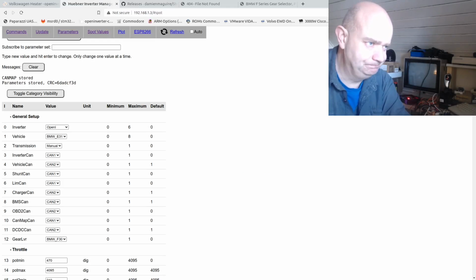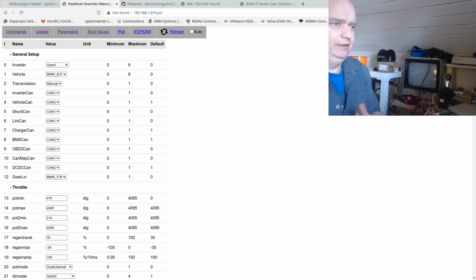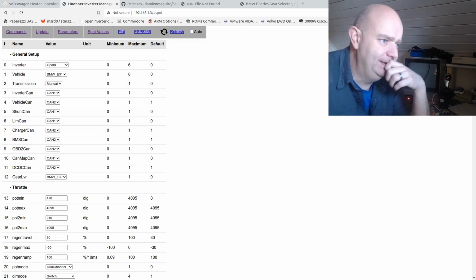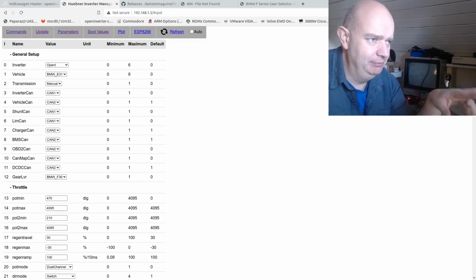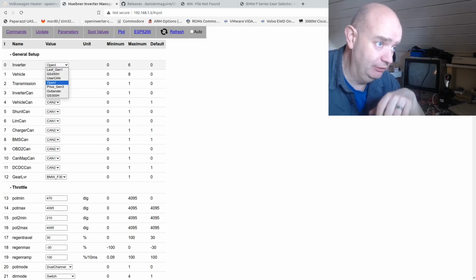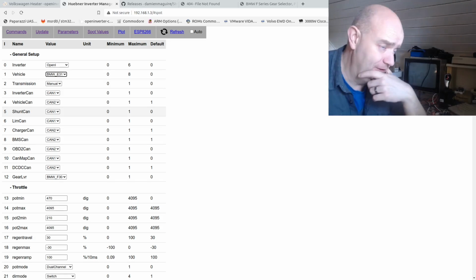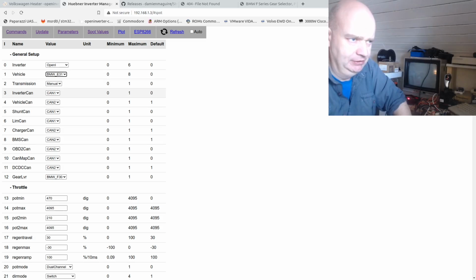So let's have a look here at our parameters and we'll get started. A lot of things are the same here, so I'll skip over things that are broadly the same as have been in previous episodes. So our inverter list, vehicle list, whether it's a manual or an automatic, excuse me, and then you can decide which CAN bus your inverter, shunt, limb, charger, BMS, and so on are connected to.